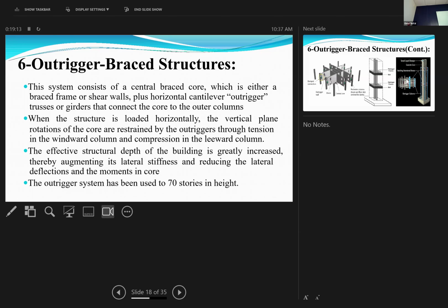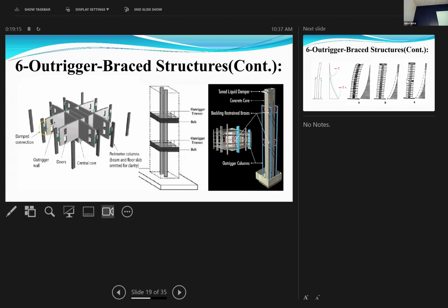So let's see how it looks like. It's something like this. This is an outrigger in the X direction, and this is an outrigger in the Y direction. And by the way, you can make multiple outriggers. Sometimes one of them is not enough, so you need to have one here, one here, and one there. But they work better if there's a shear wall holding them in the middle. But it's okay to put them and connect them with columns, all of them as columns.